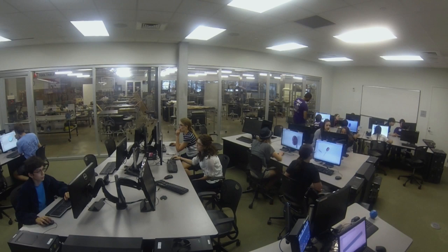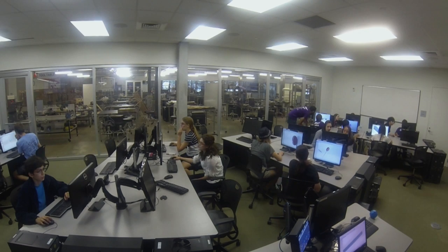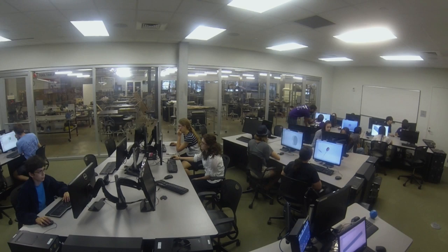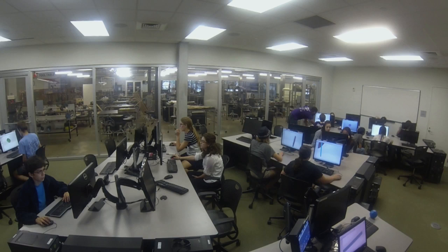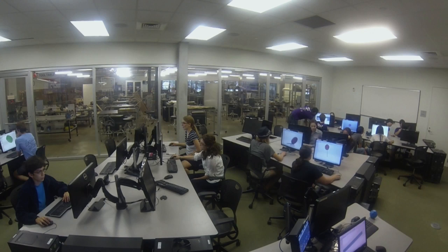What's the center though? What do I do? So there's a couple different ways. One, you could measure between these two lines, and then you would plot a section there and divide it by half. Basically, so one way. The other way, you would just take the edges and draw another construction line. Scroll down. And now you just attach it to one of these points.